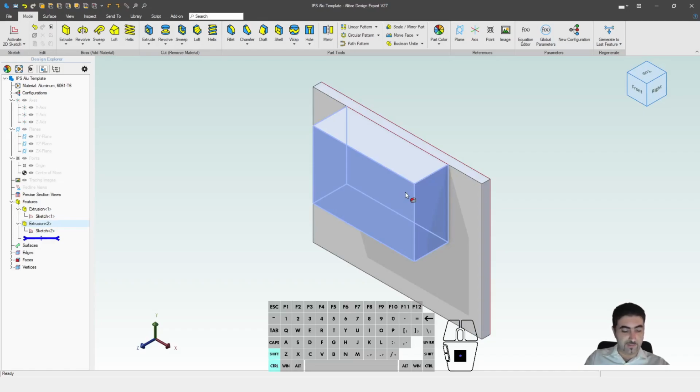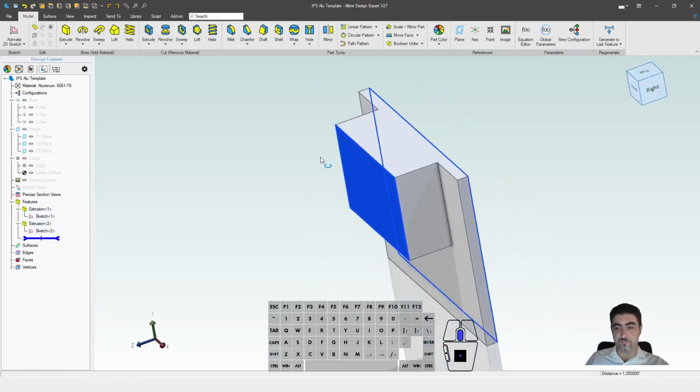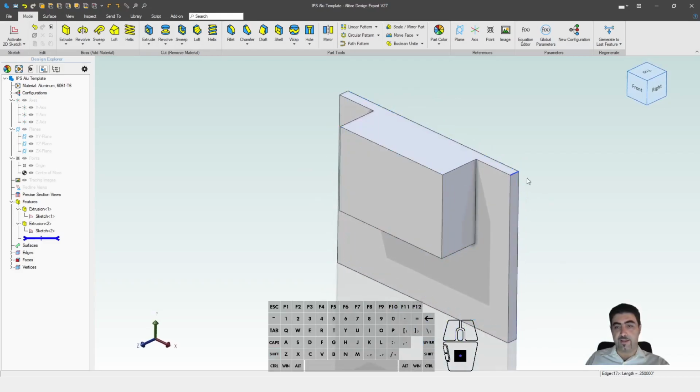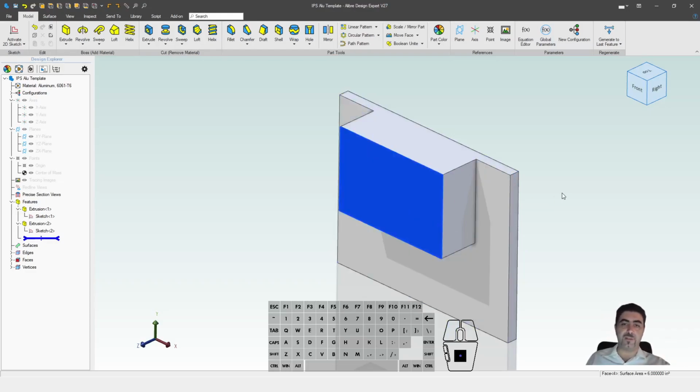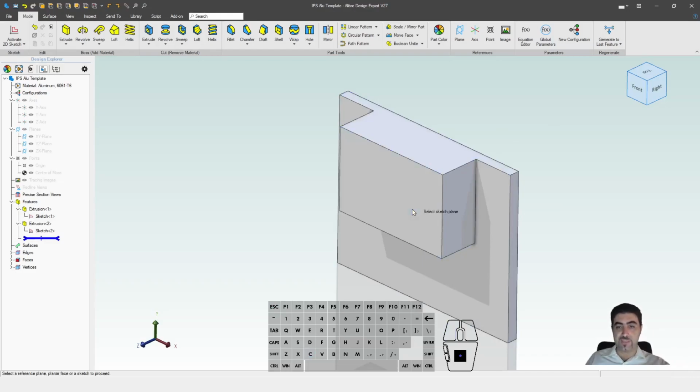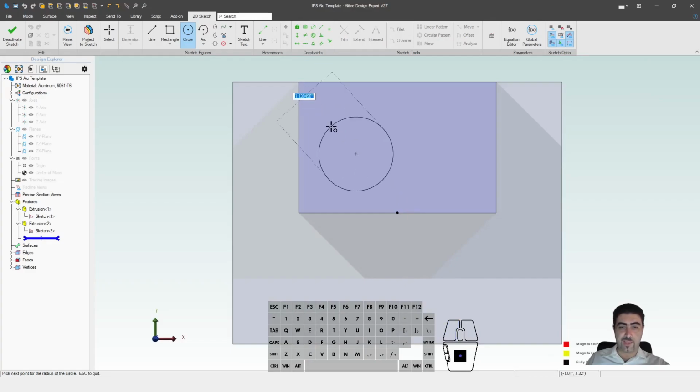In the drawing, let's hit Control Shift K and hide the sketches. So this height is called to be 1.25. I know I already made this 0.25, so I only need an additional inch to get there, right? And similarly, without moving my mouse, C, click, now I'm creating a circle, right? As soon as I move my mouse, I get that blue highlighted 1.75. Oh, let me do it, 1.75, so you can see the input overlay again, enter, and then Shift V.